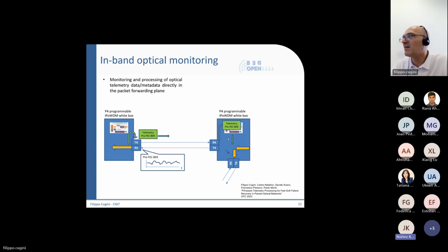But for example, in this case, you are trying to look for something with more degrees of freedom, in the sense that it can adapt to the different types of channel and the different requirements of the user that you can have. In this case, to expand, for example, the bandwidth that is required, it will change the channel coding that we are using. So we should have different types of FEC or pre-FEC, and so that is my question. Are you trying to look at something that gives you more degrees of freedom?